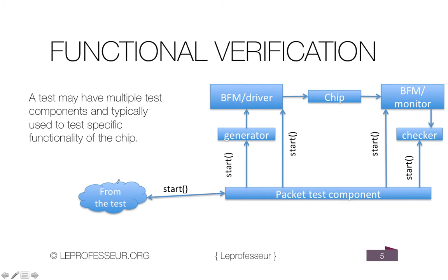So let's say from the test it starts, you communicate with the packet test component, there is a generator that communicates with the driver, and the driver is driving the stimulus to the chip. Okay. And then the output of the chip is monitored by the monitor module, right? The monitor module communicates with the checker, which keeps track of which stimulus is being compared, what was the result, what was not the result,